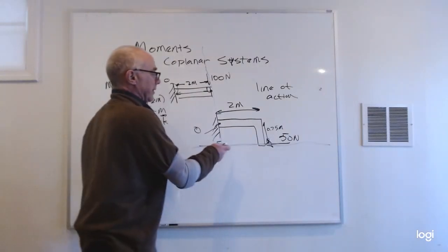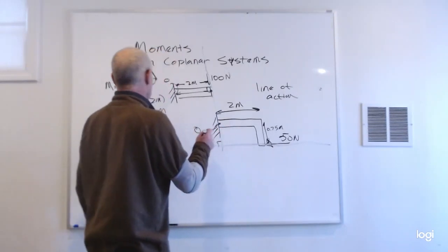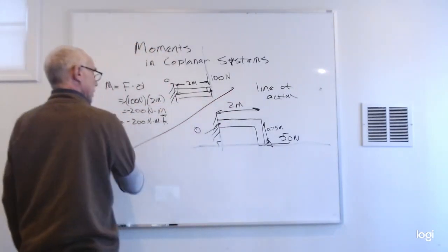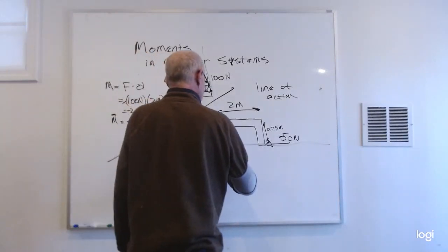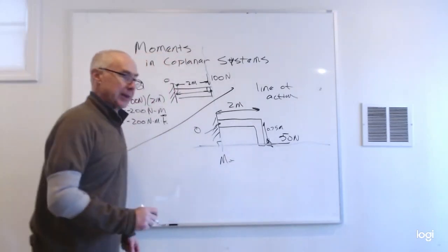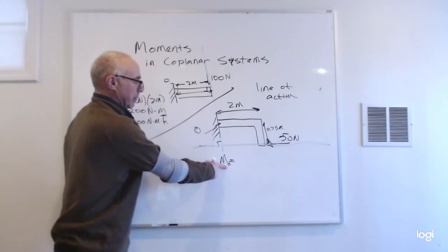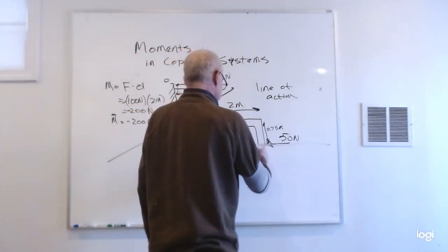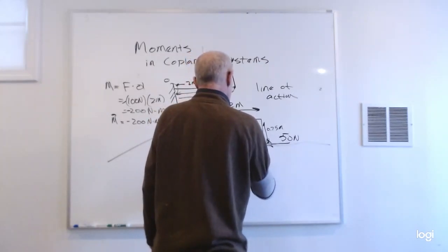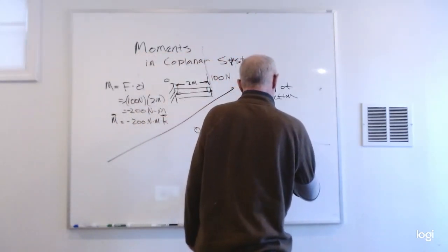Now I'll just multiply it out. We already have that distance here, 0.75 meters. So the moment here, I'll draw a line here so I can distinguish that problem. With this problem, the magnitude of that moment, and I'll put a little subscript O, which implies the point we're evaluating the moment about, is equal to that 50 newtons times our 0.75 meter perpendicular distance.